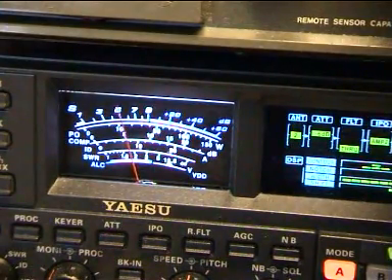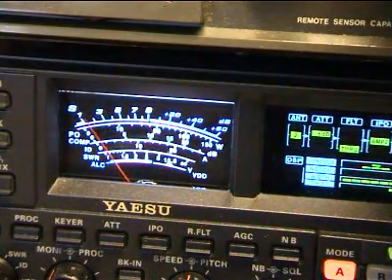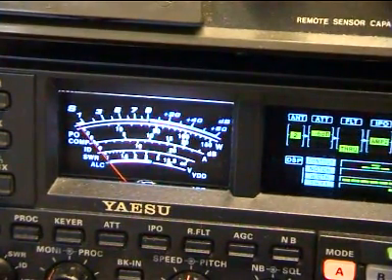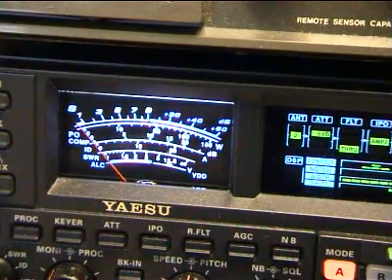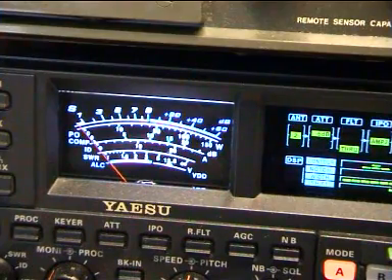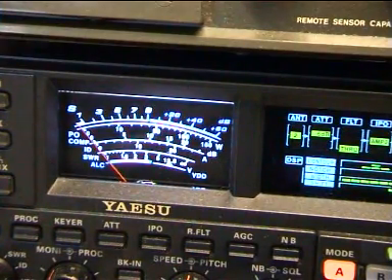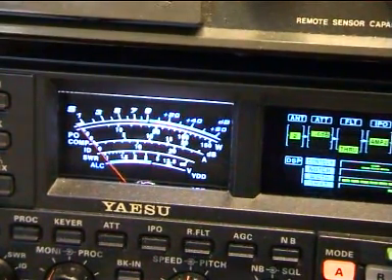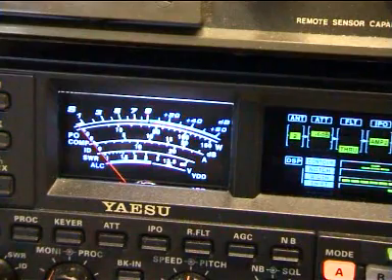I now adjust my device down to the point just below where there is no deflection from ALC. This will now give you the maximum output available, but also the cleanest signal possible under these conditions. I always recommend operating with zero deflection on ALC, as this will give you the best possible quality of transmission. That concludes setting levels for TX.